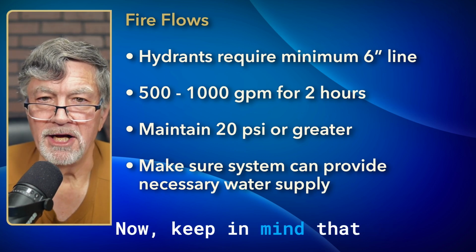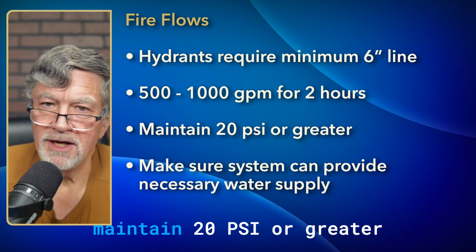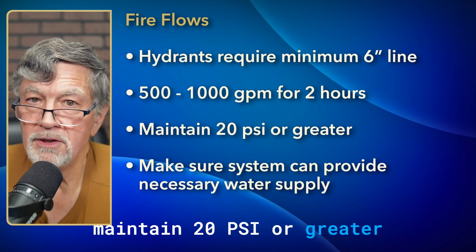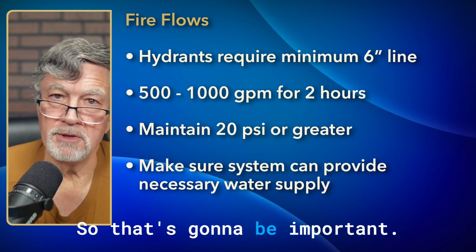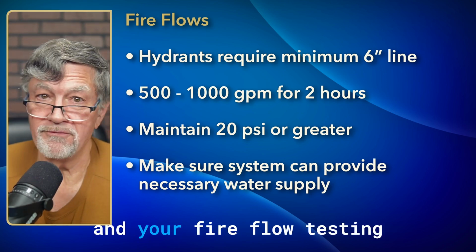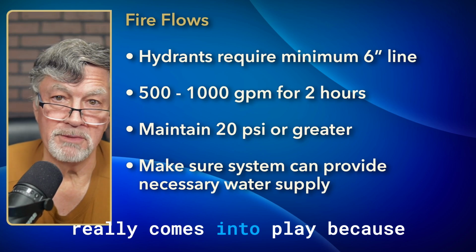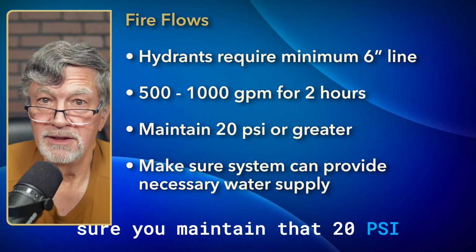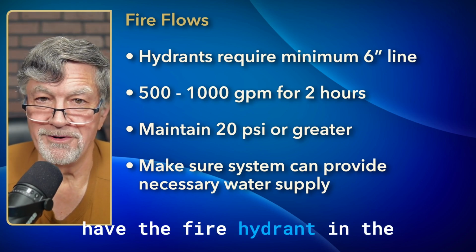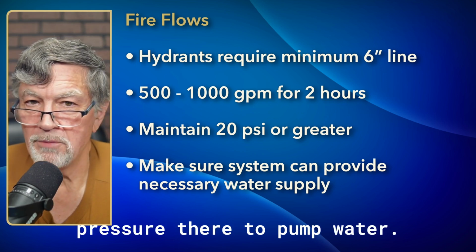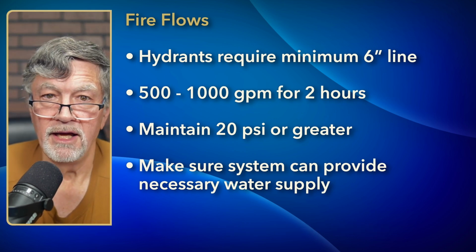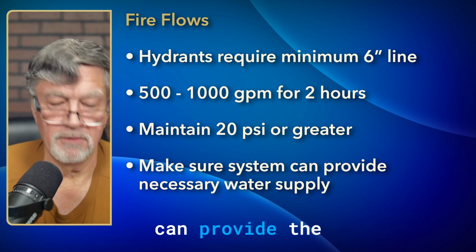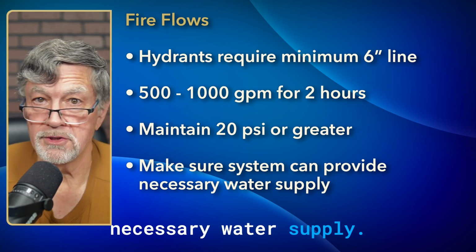Now, keep in mind that you're going to need to maintain 20 PSI or greater throughout the system. So that's going to be important. That's where your fire flow testing really comes into play, because you need to test it to make sure you maintain that 20 PSI. It doesn't do you any good to have the fire hydrant in the water if there's not enough pressure there to pump water. And make sure your system can provide the necessary water supply.